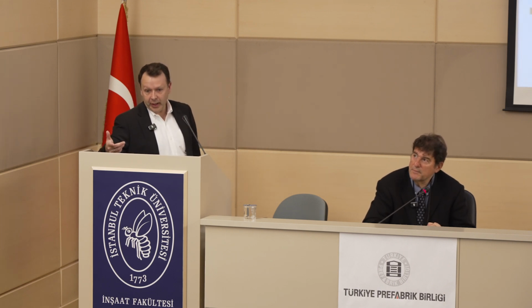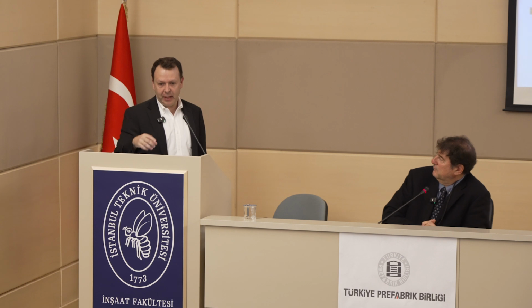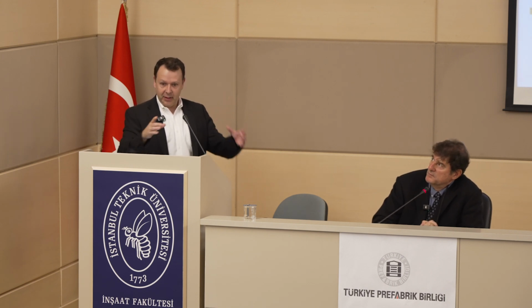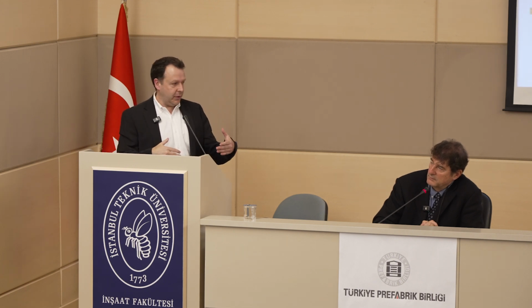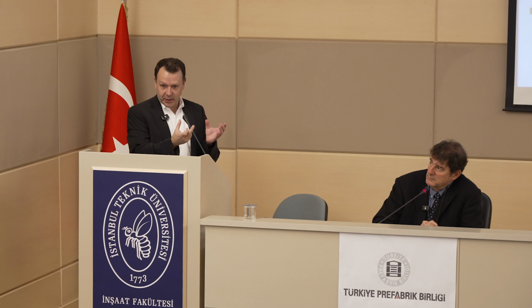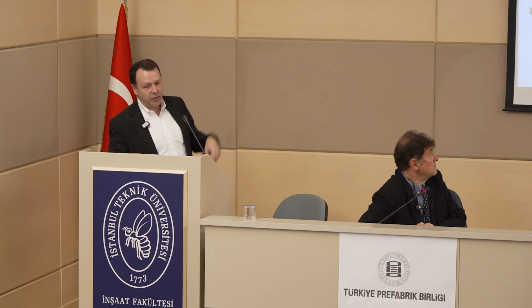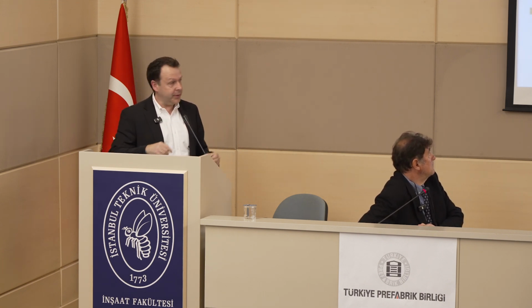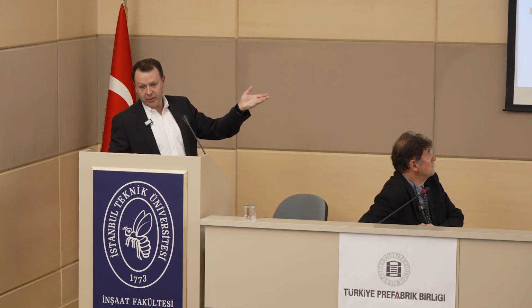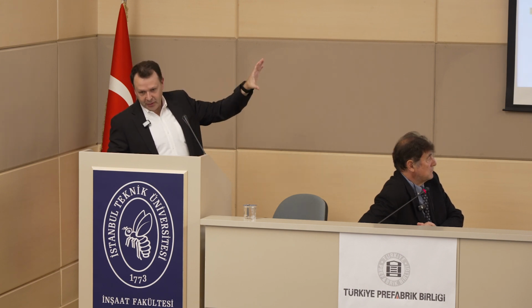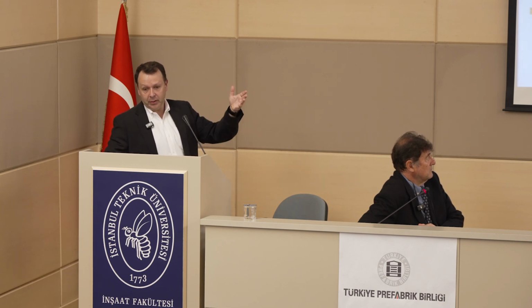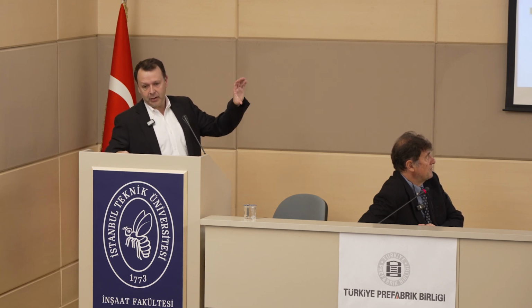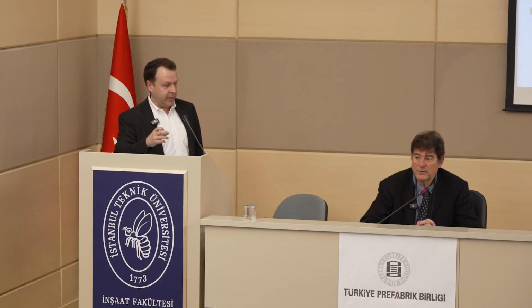Yes, when you're doing your checks in selecting your beam and column sizes, that's implicit already as you're coming up with the initial sizes. I have heard that often in Turkey, your beam widths and column widths are similar, right? Here, for our moment resisting frame, they do not have the same size, our column is larger. And then we do check as we are putting in the reinforcing steel, but if your column is already larger, if you're working with a 1% drift, 1% reinforcing steel ratio, you would expect to see a larger capacity straight away. But we do have to check that the capacity in the column is at least 1.2 times the capacity of the beams.